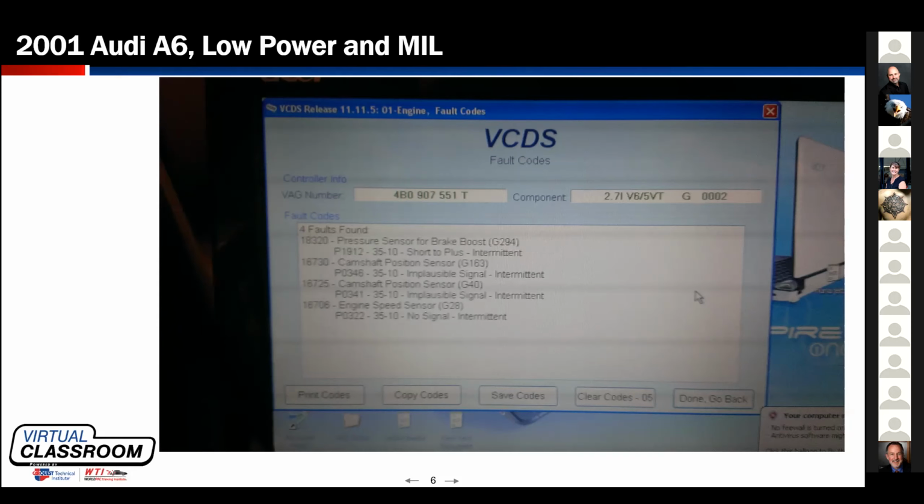But before I install this engine, and here's one of the keys to this, before I install the engine, I'm going to put a fresh timing belt on it. I'm going to put a water pump on it, and I'm going to go through and seal up all the common oil leaks that these vehicles had, fix the tensioners, on and on and on. So he's trying to do the most complete job he can to this used engine, plop the trans in it, put it all together, and boom, be on the road.